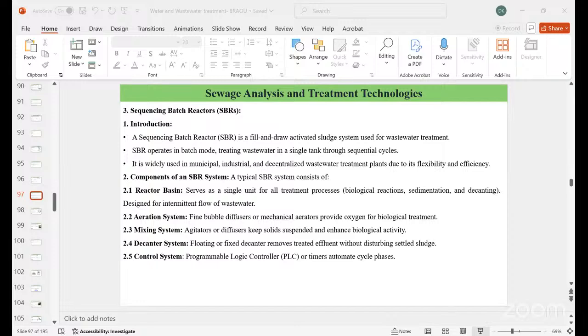So coming to the chlorination process, the main mechanism involves chlorine in various forms, either liquid, gas, or in the form of sodium hypochlorite or calcium hypochlorite, and this basically reacts with the water to form hypochlorous acid, which is a powerful oxidizing agent that disrupts the microbial cell membranes and thereby inactivates their enzymes.